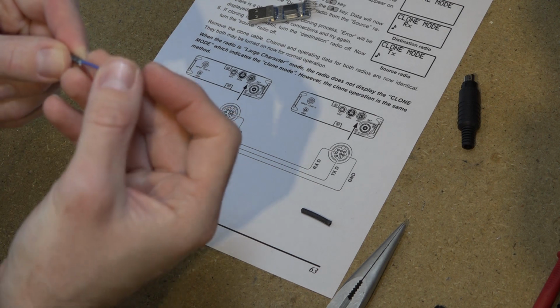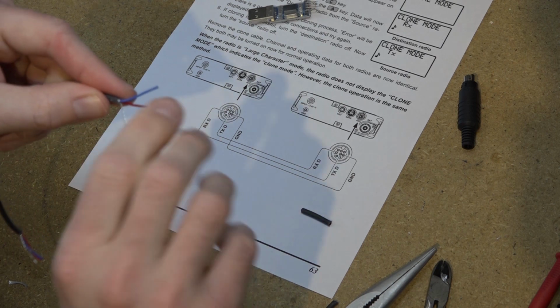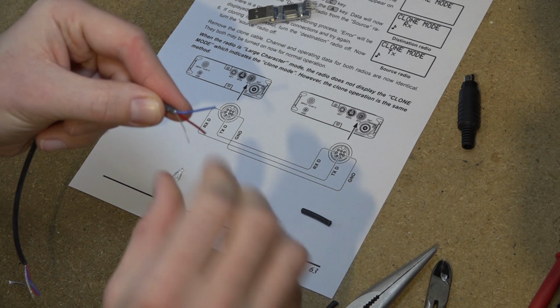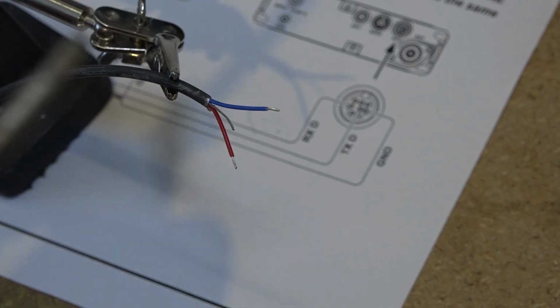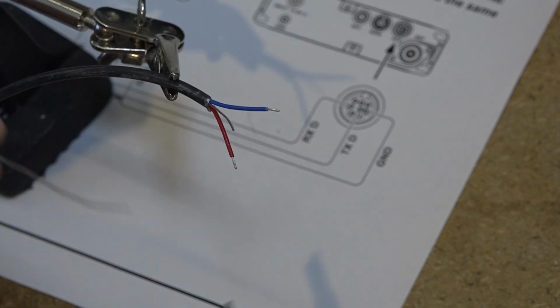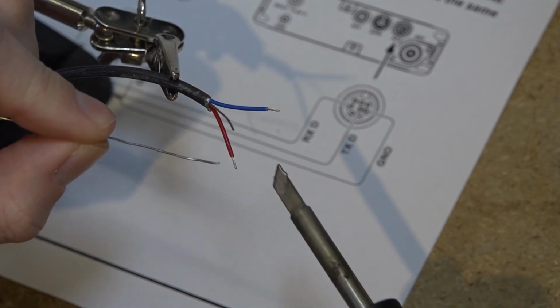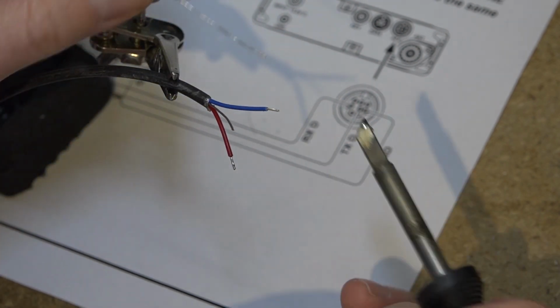Now, once you've stripped off a little bit of the insulation, you'll just want to give these wires a quick twist, just to make sure all of the different strands are held nicely together. For the inner wires, you don't need to take off too much of the insulation, just a few millimeters. So once you're ready to start tinning those, you just want to apply a little bit of solder. You don't want any blobs. You just want to apply a little bit of solder to each of those wires, just to hold everything together